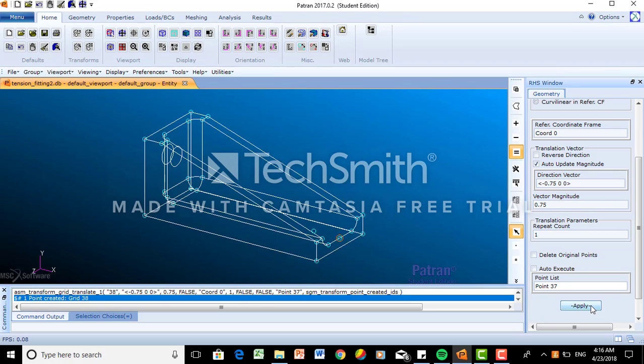And then we're going to click Apply. Now for translation vector, we're going to put minus 1.5000. Now we're going to put 2 for repeat count and select the next translate point. Then we're going to click Apply.